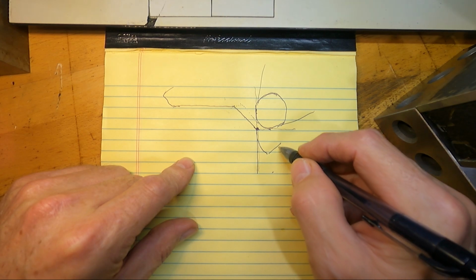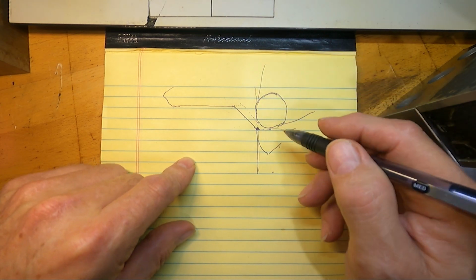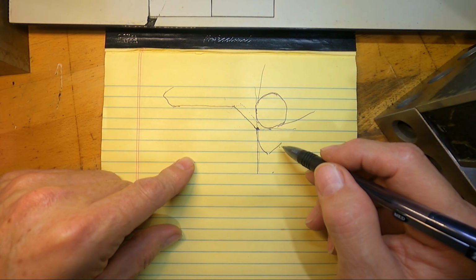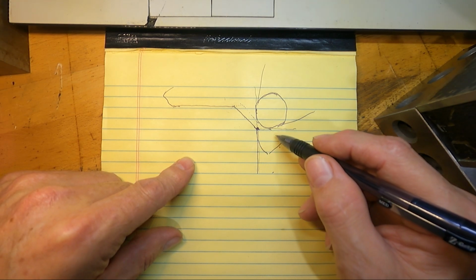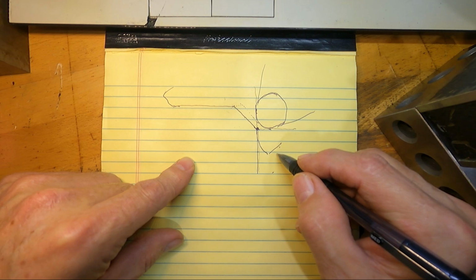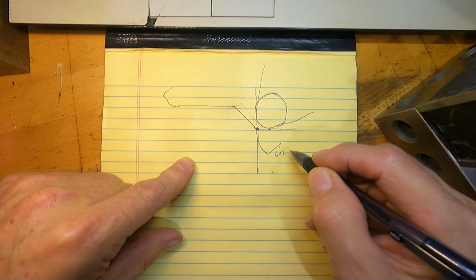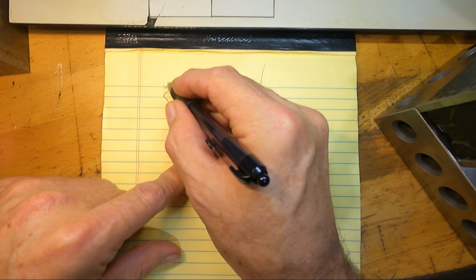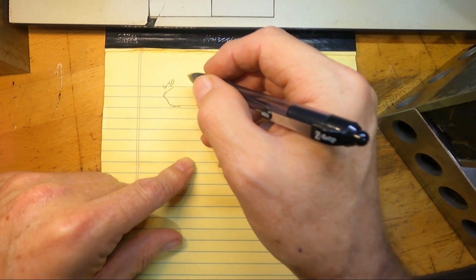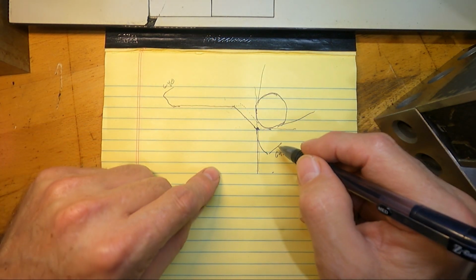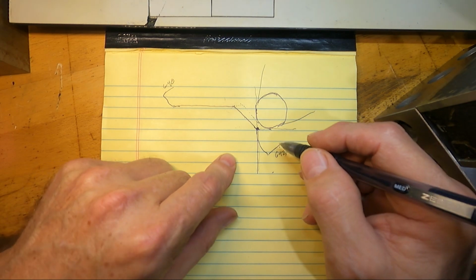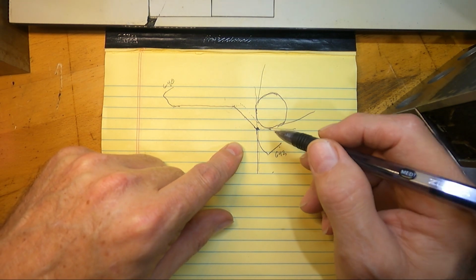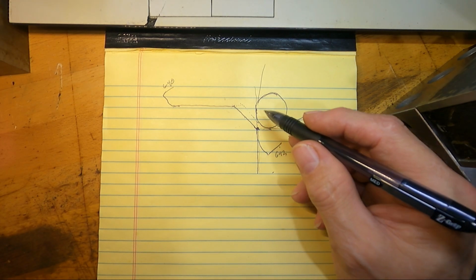So this would be the G. In this case, it's on the right hand side. I think, yeah, you're on the right hand side of the line, the contour. So this is a G42. So you have a G42 on this line and G40 on the exiting line here, and these would have to be, or should be at least, the radius of the tool or larger here.